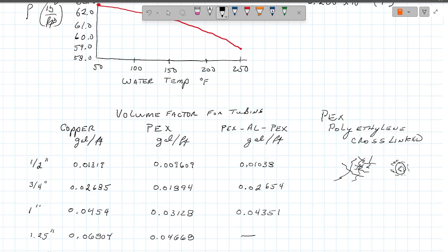Okay, and there is no sizes out there for that. So normally we don't do anything much larger than 1 inch for radiant floor systems, and if you got to get larger to get water to a zone for radiant floor, you run copper over to it and then switch over to PEX. PEX allows us to make the range of things to move around. Okay.